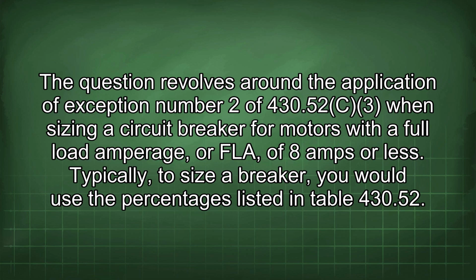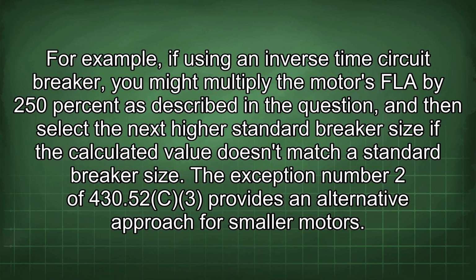Typically, to size a breaker, you would use the percentages listed in Table 430.52. For example, if using an inverse time circuit breaker, you might multiply the motor's FLA by 250%, as described in the question, and then select the next highest standard breaker size if the calculated value doesn't match a standard breaker size. Exception No. 2 of 430.52(C)(3) provides an alternative approach for smaller motors.